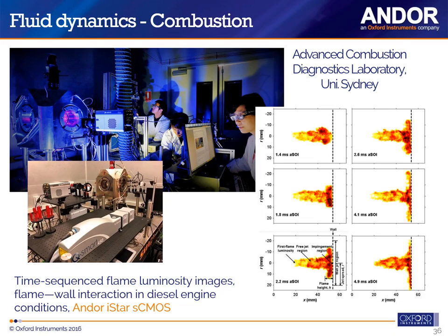Basically, the team is looking at a very accurate time sequence of the profile of the flame when it interacts with this wall, and probing particular species generated during the combustion, isolating these species and exciting them with a laser to do the likes of planar laser induced fluorescence imaging to create this contour of the flames at different times.